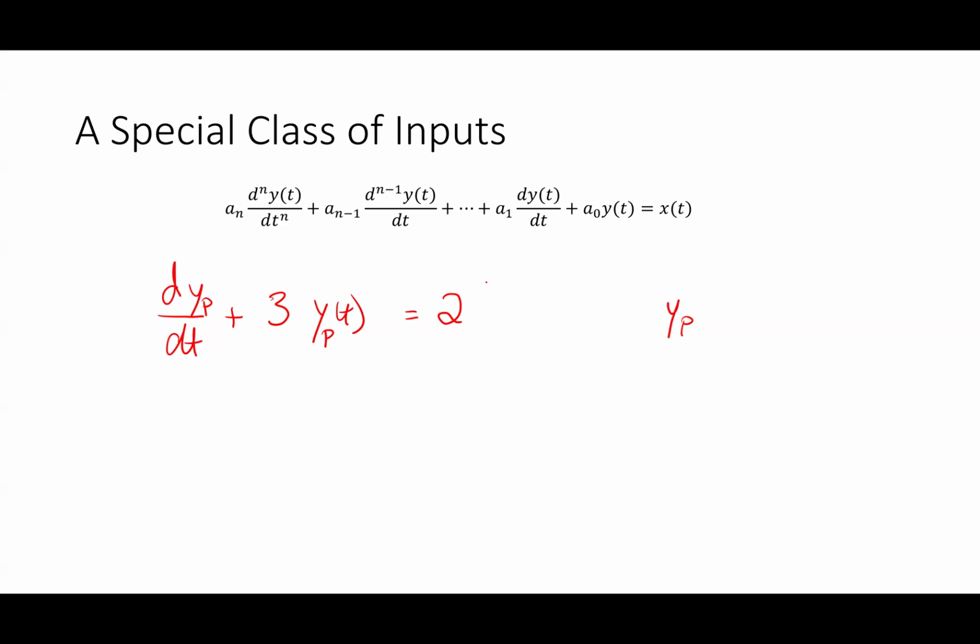Let me ask you this. If I have a differential equation, if I have a circuit, an RC circuit, what's the y if I have an RC circuit? No. What do I solve for in an RC circuit? You guys are going to tell me you took 2111 last semester, right? It might be the voltage across the resistor or capacitor. Usually it's the capacitor voltage, because the capacitor is the thing that's slowing everything down. So it's typically the capacitor voltage, or the inductor current if it's an RL circuit.